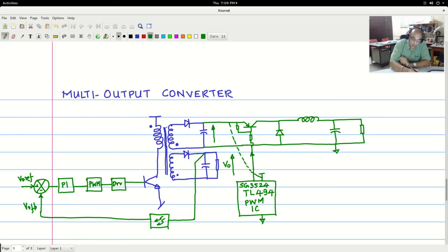And most of the ICs have inbuilt internal op amps too, which can act as comparators and difference amplifiers, and also even PI controllers. You can make a PI controller with an op amp using a very simple circuit topology like this.